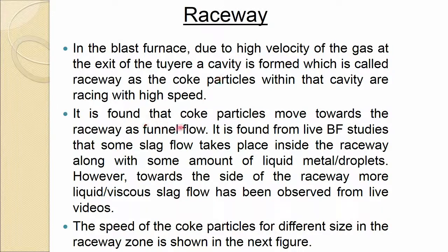And it is found that coke particles move towards the raceway as funnel flow. It is found from live blast furnace studies that some slag flow takes place inside the raceway along with some amount of liquid metal droplets, which you have seen just now in the previous video.